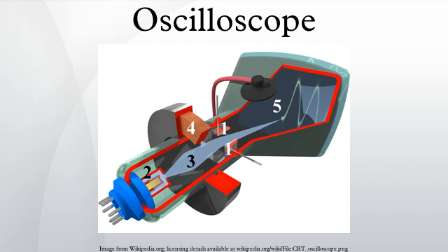A typical probe uses a 9 MΩ series resistor shunted by a low-value capacitor to make an RC-compensated divider with the cable capacitance and scope input. The RC time constants are adjusted to match. For example, the 9 MΩ series resistor is shunted by a 12.2 pF capacitor for a time constant of 110 microseconds. The cable capacitance of 90 pF in parallel with the scope input of 20 pF and 1 MΩ also gives a time constant of 110 microseconds. In practice, there will be an adjustment so the operator can precisely match the low-frequency time constant.